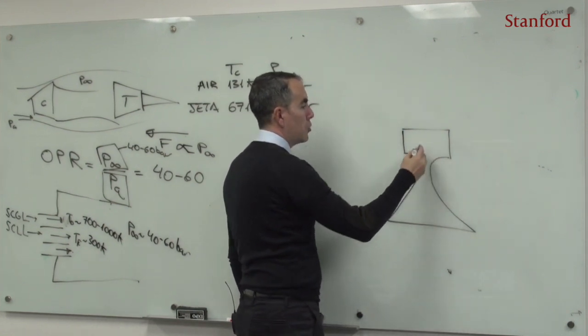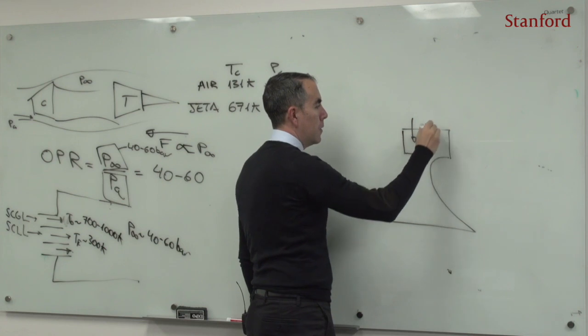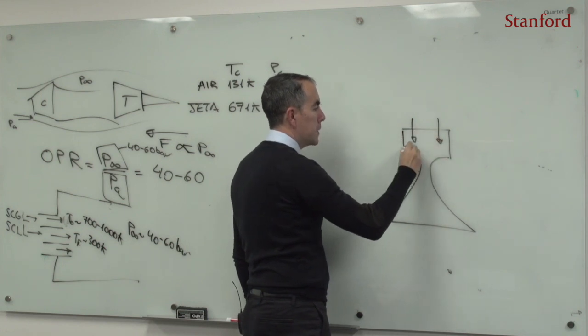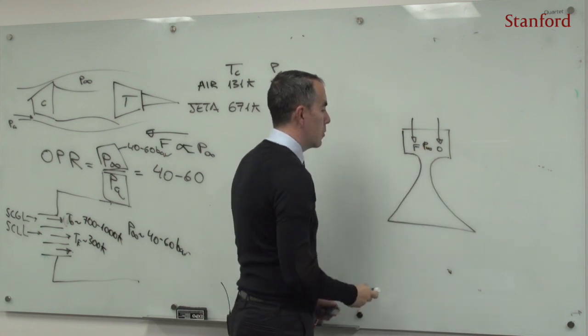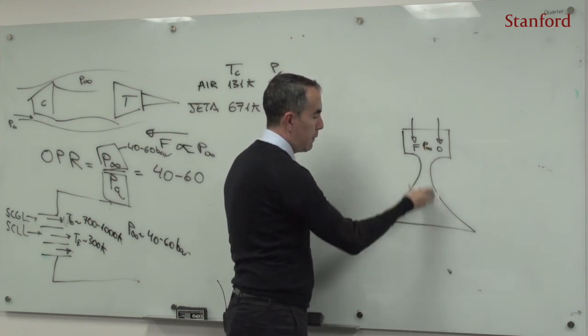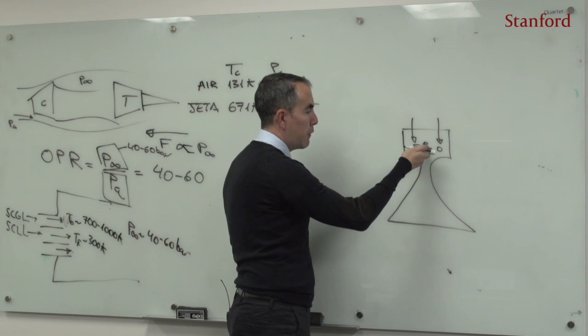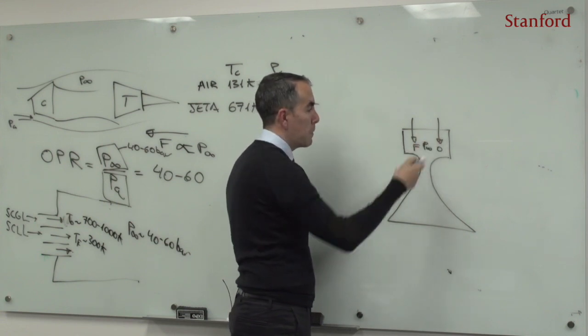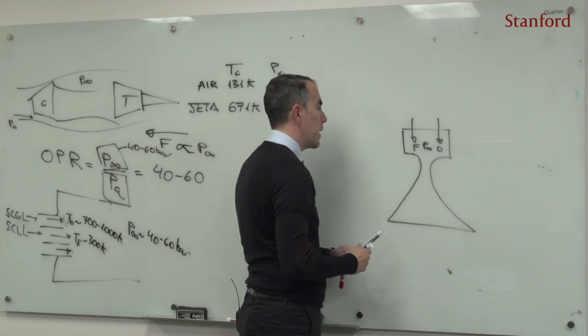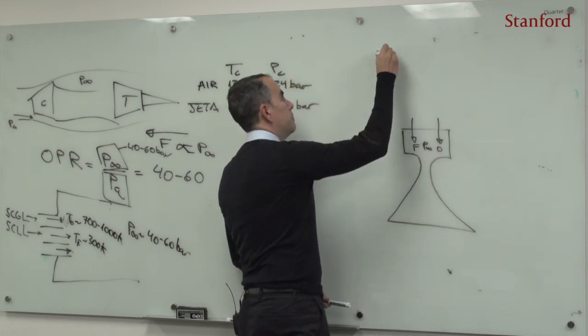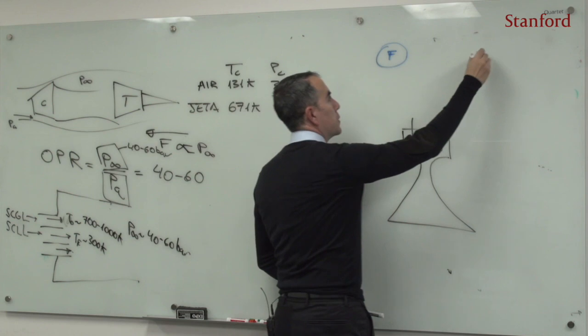Right, so this combustor is going to be again ingesting fuel and oxidizer. So I'm going to have some pressure here in the combustor. So here I have a supersonic flow, the nozzle is choked, and therefore as a result I'm supposed to have high pressures here in the combustor. So the combustor, as I said, is going to be fed by fuel and by oxidizer.